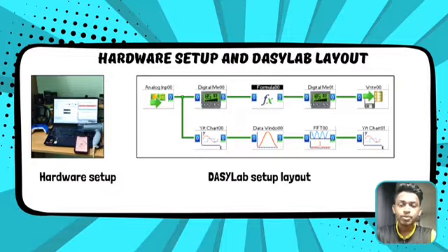Following that, we will navigate to modules and click display and select Y/T chart module to measure the time frequency domain. Next, we will navigate to modules, click signal analysis and then choose the data window. The data window in DASYLab is a feature used to define and manage the portion of the data stream that is processed, displayed or analyzed at a given time.